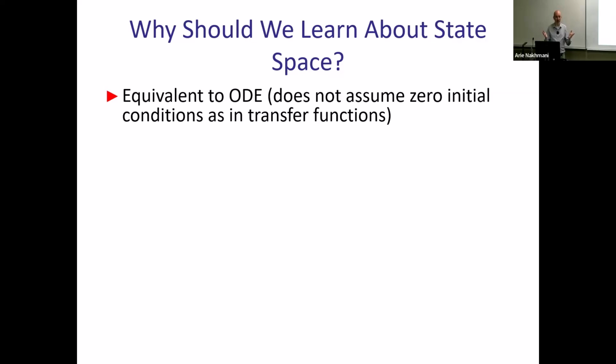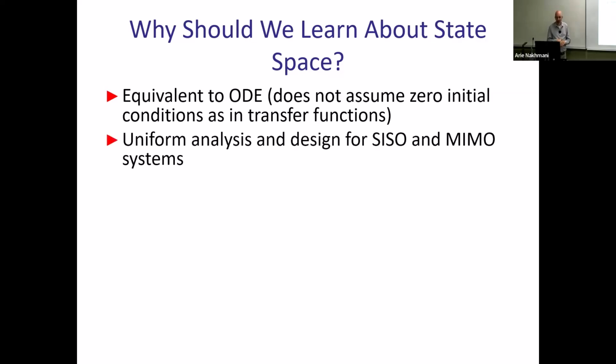Now, first of all, this is very good to learn about state space because it's completely equivalent to the ODE. You have initial conditions, you have everything which is related to the original differential equation. So you are not losing any information. Now, we can get exactly the same analysis for SISO systems, which is single input, single output systems, one input, one output, and multiple inputs, multiple outputs systems, which is more natural to work with in reality, right?